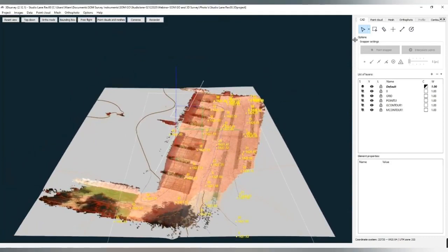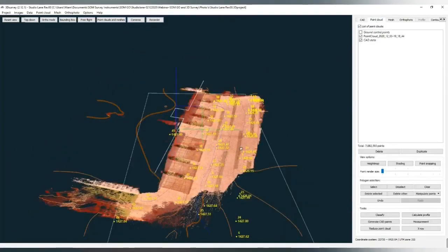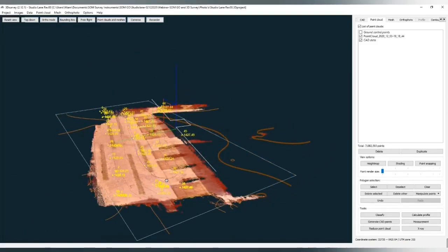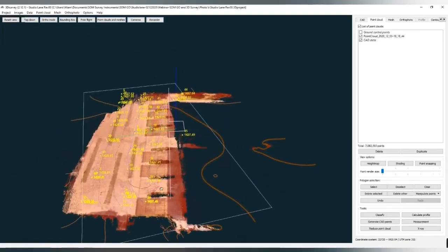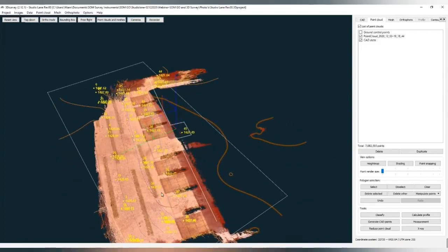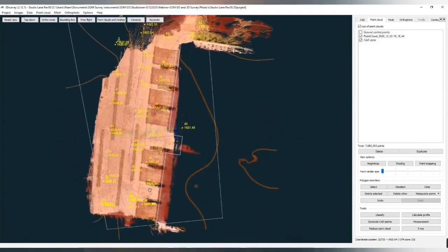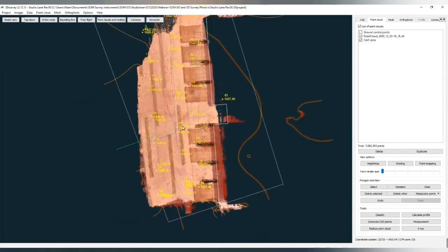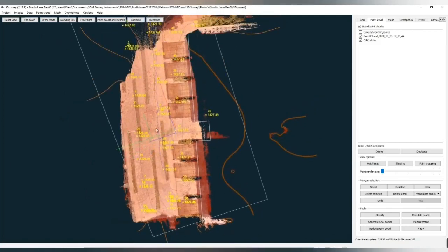And we can really compare some points manually with this, but so far we can really see a good comparison from the DXF data that was imported onto the point cloud. As we can see here, the data points that was imported all have heights. So a good example and comparison will be to take those existing GPS measured points and measure them with what we have had and what we have processed the heights to be.